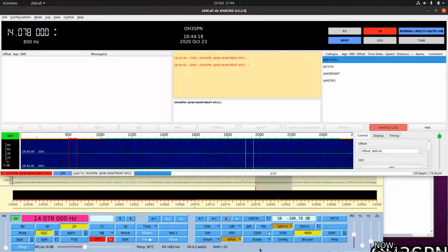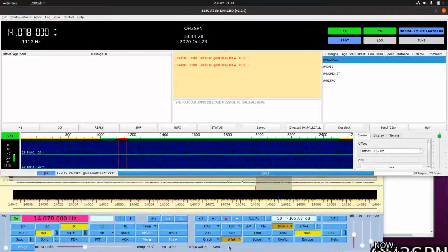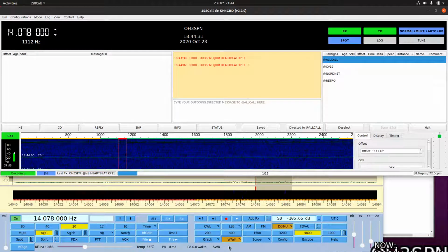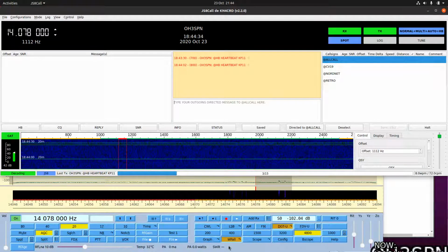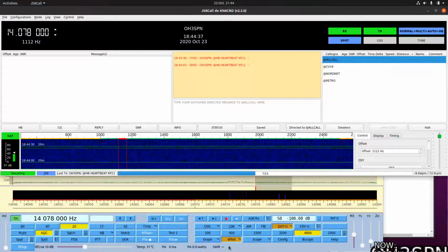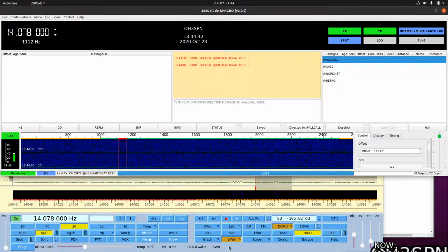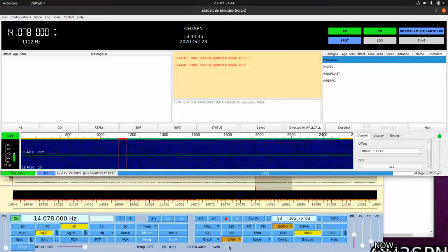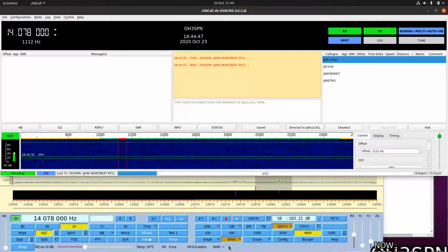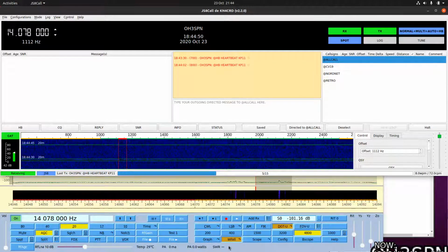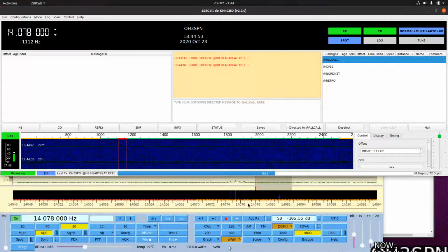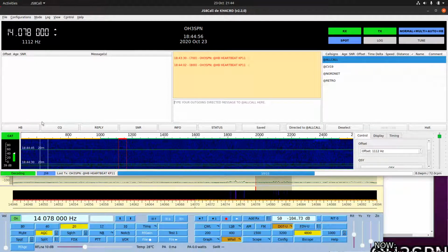Right, so SWR at this part of the band is 1.5 to 1, and we've got 6.2 watts output from the Hermes SDR. Yeah, it's a 5-watt radio, but it does a little bit better on some bands. I know some people reduce the drive power to keep it to 5 watts, but it's a LDMOS output. And to be honest, you can drive it full power into a very bad load, and there's not been any reports of failures as far as I'm aware. And it does have a thermal cutout as well. So, right, there's no activity on 20.